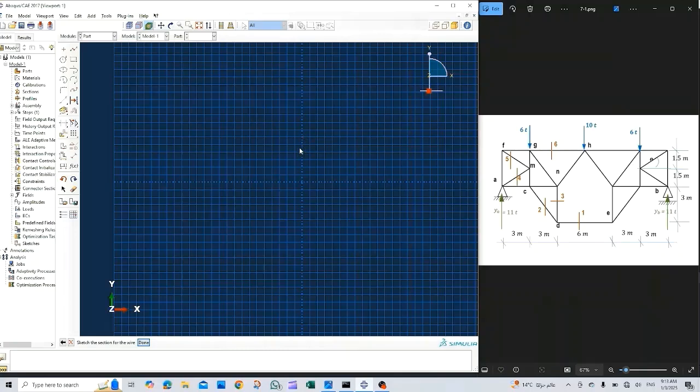Okay, we will start drawing a rectangle. Choose the icon of rectangle from here. Just click on the center 0, 0 here and click anywhere else. We have our rectangle drawn. Then we dimension here. Just click the first point of the line you want to dimension, the second point here, and click the location for the dimension.